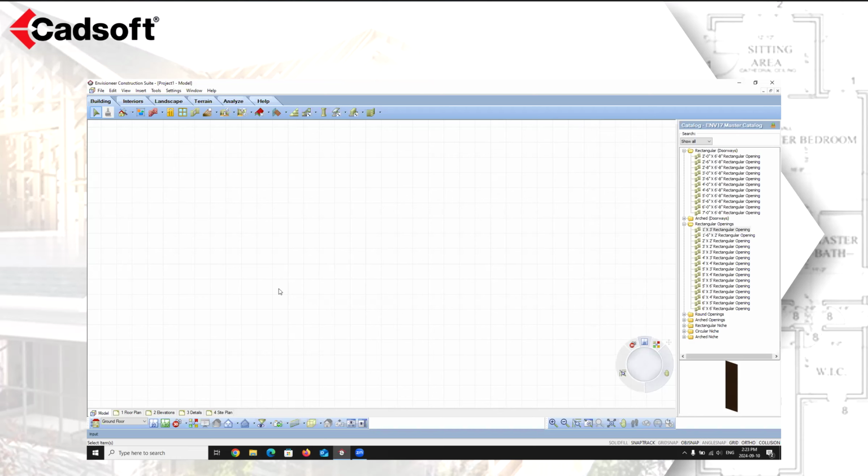Or trying to place stairs within 2 walls. Again, collision will prevent that from happening. So what you need to do there is simply uncheck collision to turn it off, and then place the object where you want it, rotate it around, snap it to the corner where you want it to be, but I do always recommend turning collision back on.